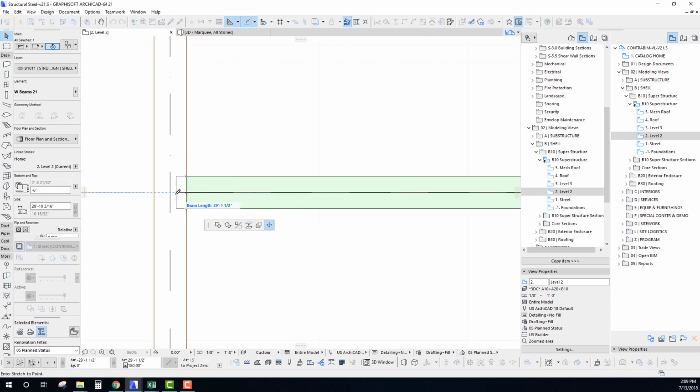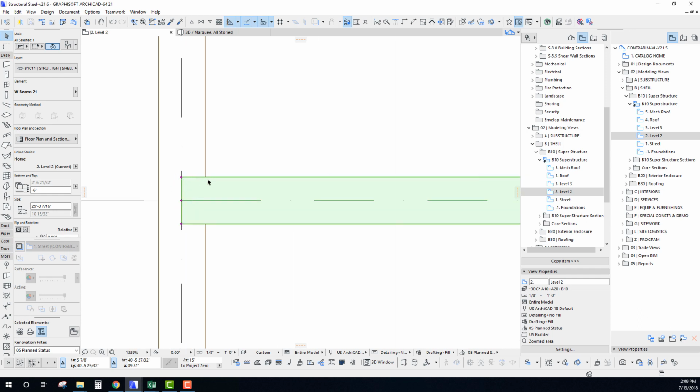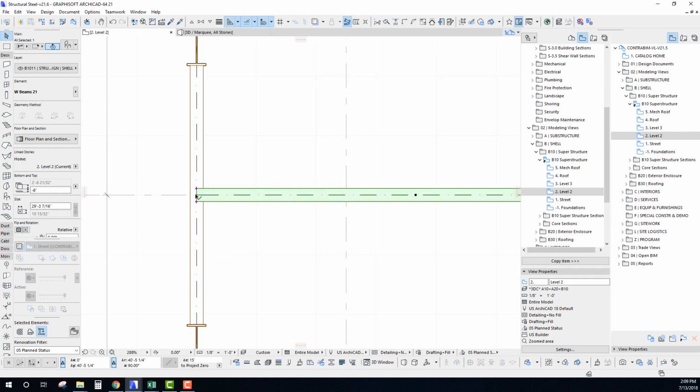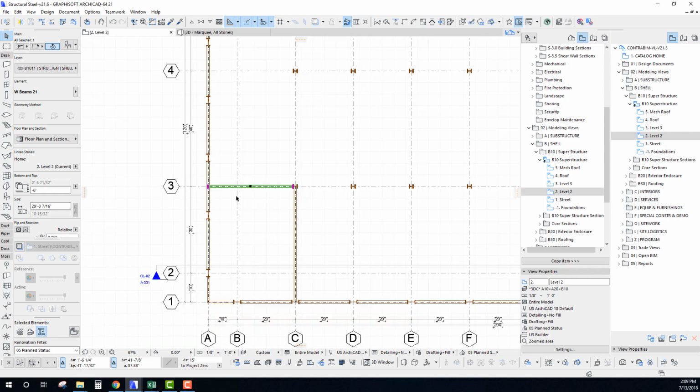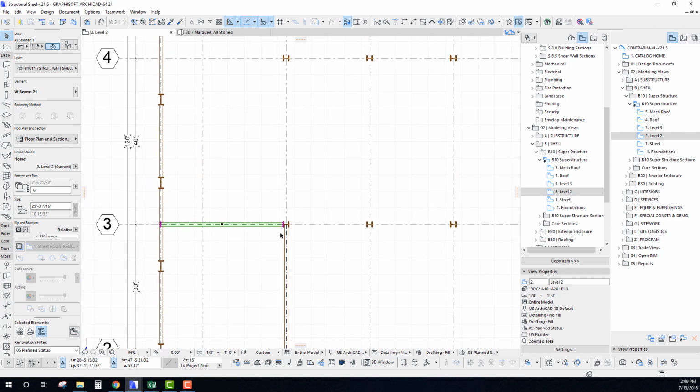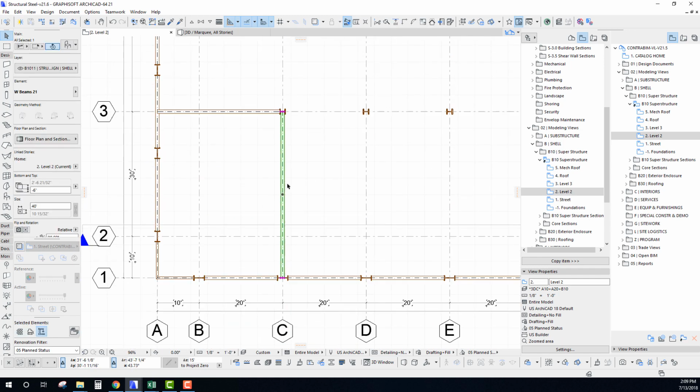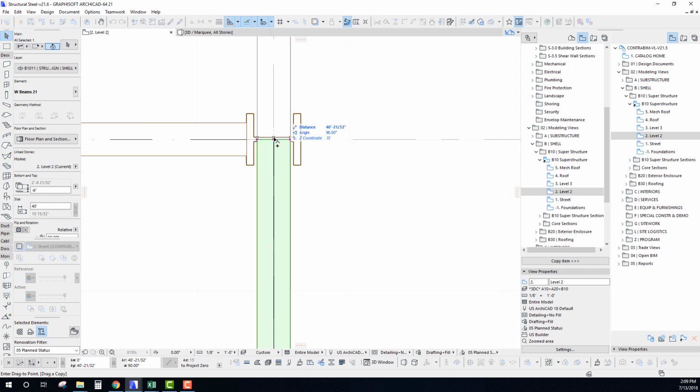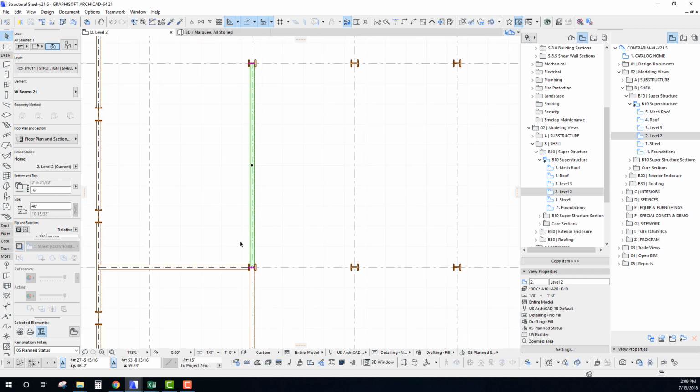In the case of being conservative and making sure that you have that full cut length, it might make sense to actually draw that a little longer, because if you were thinking about how this might get detailed, you'd probably notch the top and bottom of those flanges, and you might have a bit of a protrusion of that center web into that beam for that connection. But okay, so let's continue now. And once we get this all in here, it's going to go very, very quickly.